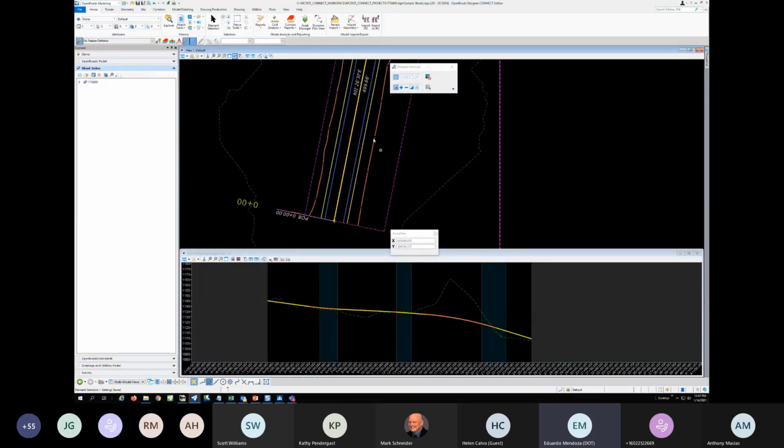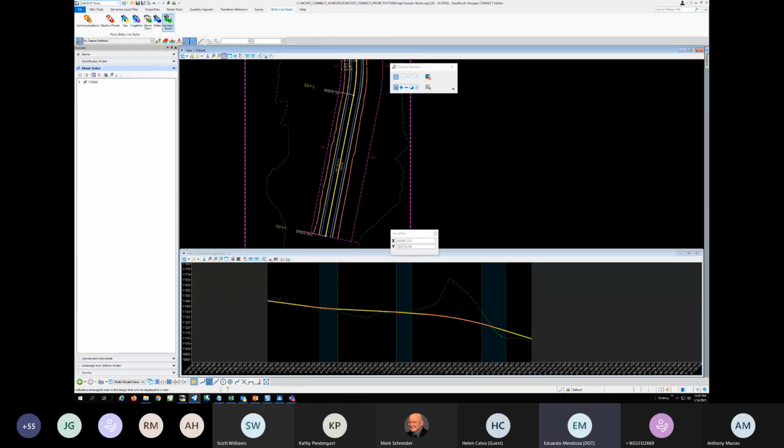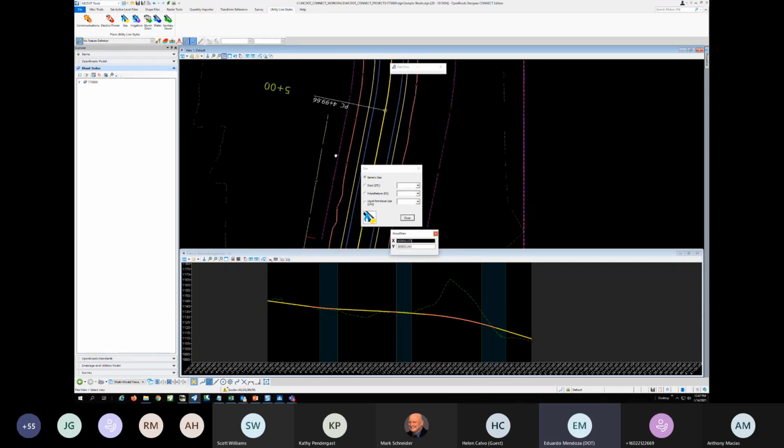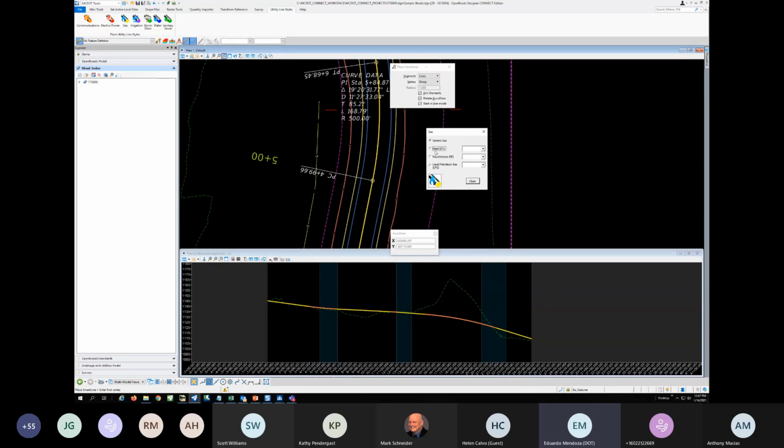And one of the things that I wanted to show you as well is that everything is annotation scale. I'm going to go to MCDOT Tools. In the MCDOT Tools, you see we have tools for placing line styles. So if I go into, say, for instance, gas right here, I could pick a generic gas line, and you'll see that the scale of that gas line is appropriate for the scale that I'm working on. And the software is smart enough to know that if I go from, let's say, a 2-inch steel line to a 16-inch steel line, it already knows that it has to be a multi-line, okay?